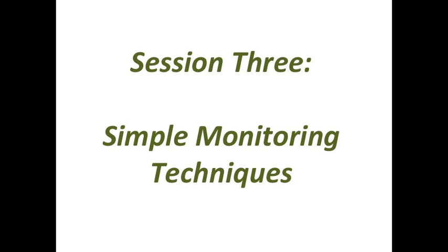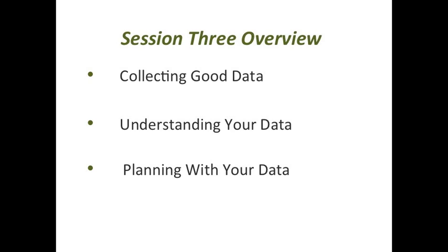Okay, so welcome to session 3. We'll be looking at ways to collect and use really good energy data in this session. Session 3 is a really simple one. First, we're going to look at simple, easy ways to collect good data using fuel meters, electricity meters, and logbooks.